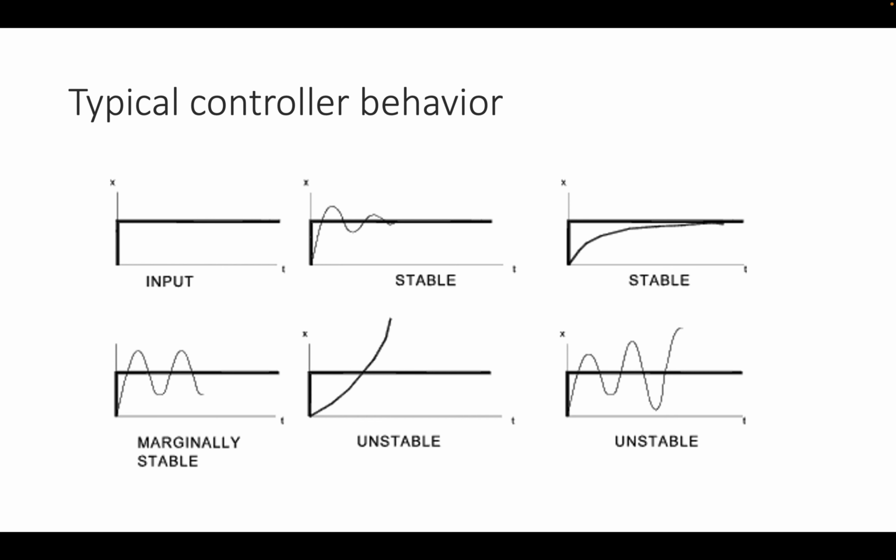Now, when you did this experiment in Webots, you have probably only seen this behavior here. I then asked you to increase the gain quite tremendously, where you got into a marginally stable situation where the robot just turns back and forth, back and forth. Now, the robot isn't fast enough to exhibit this kind of overshooting behavior, because we are only giving it 32 milliseconds.